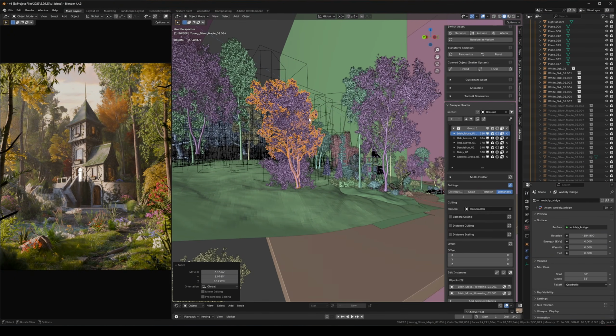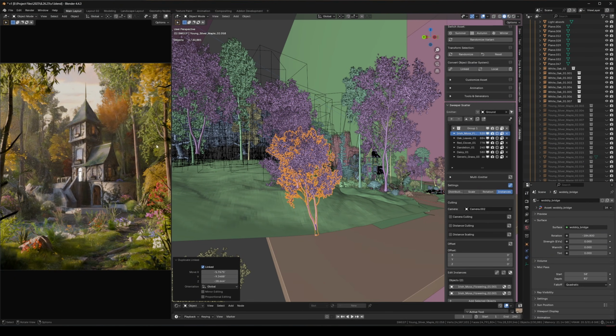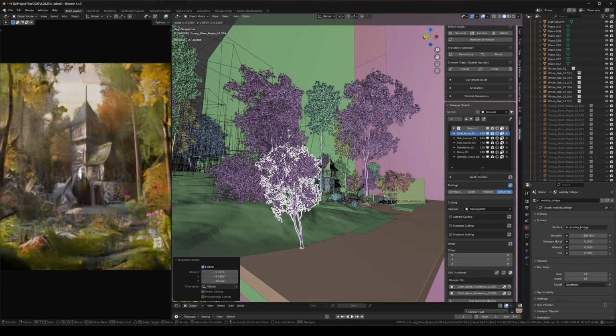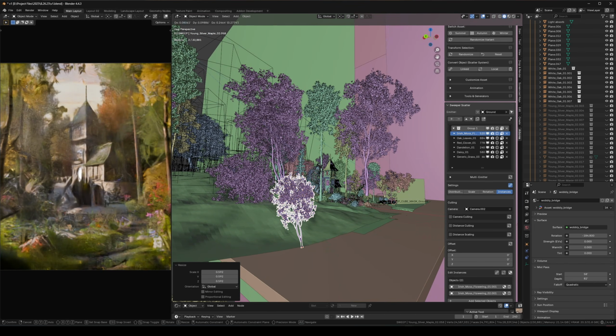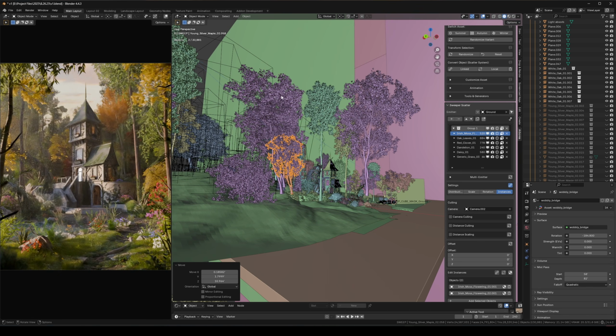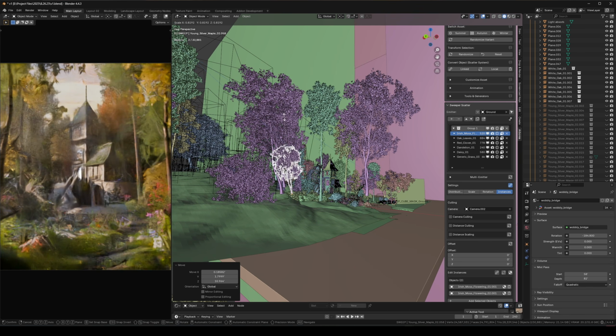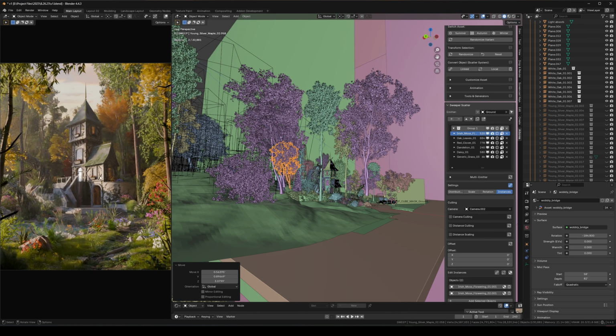Let's try something down here now. So Alt D. And yeah, I just moved this to the bottom of the cabin. Lighting is pretty even right now, so let's make this a bit smaller so that patch isn't so large. Then we can move this back up. Okay, so we got a shadow right there. Let's go a little bit lower. So I'm scaling this down, moving it back up. There we go. And that's looking pretty good, but this still has this big wall of light.